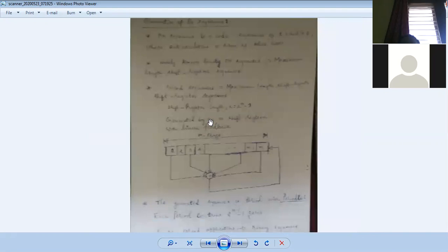That is the PN sequence, the code function here. It is as simple as this: a shift register of length m, containing a number of bits, m and m minus 1. Initially it is loaded with some coded value, like 1000. For each bit, the values go to a sum, then to the linear feedback. Each bit is shifted by one towards the left. As it shifts, the same bit is transmitted and also fed back. Likewise, the PN sequence will be generated.